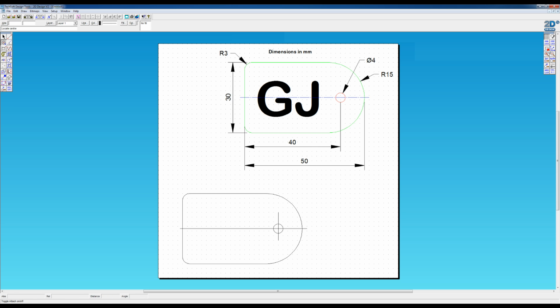So we'll double click, turn intersection off. Okay. Turn that option off and put grid back on. And then we're going to right click to get out of drawing a circle. We'll delete that line there. Then what we'll do is we'll add some text. We do that by clicking on the ABC tool. So we'll click on that once, click where we want the text roughly, type it in.